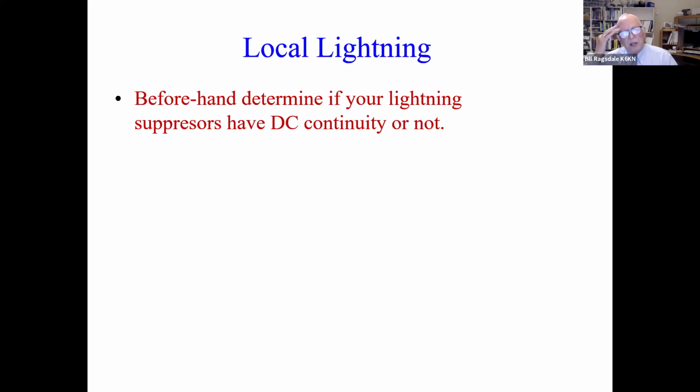Another possibility, we don't have as big a problem around here, but in the southeast areas and South US, lightning is a real problem. Your lightning suppression devices, whatever style they are, some will withstand strikes nearby. They'll withstand transients. They'll cure themselves, but at some point they're sacrificial. With a big enough lightning disturbance, they will be damaged, and they'll either fail open circuit or short circuit. But they failed.